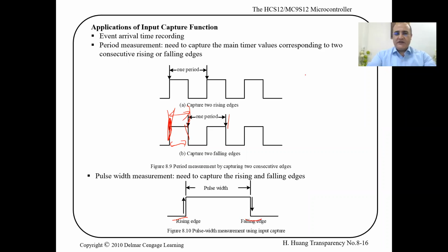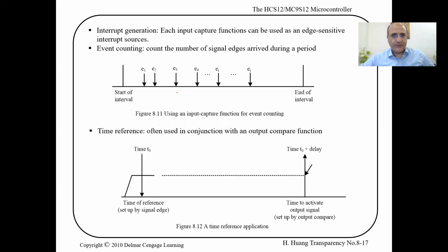In this case, you measure the pulse width, just like here. And again, it's not necessary that these events, rising edges, are just square waves coming from a function generator. These can be coming on a pin from a push button, or a button tied to your door, or coming from a sensor like a sonar sensor, where you need to know the time between an event that happens and another event. Anyways, a rising edge, you can generate it for any application you want, using any way.